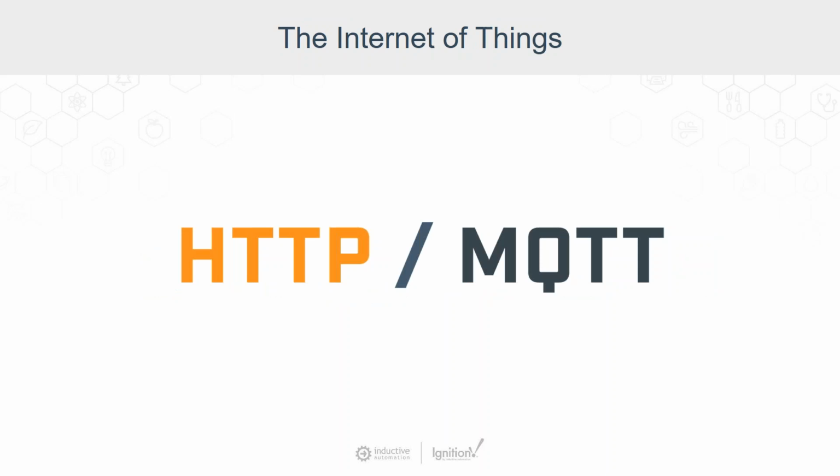And what I'm trying to do here is explain that for the industrial world, and getting these applications and the data that's there, we are equating the Internet of People to the Internet of Things. So for the Internet of People, it is HTTP and HTML. For the Internet of Things, it is MQTT and the Sparkplug specification, which is, again, that open payload specification for what is being transported. So MQTT is the transport mechanism, and Sparkplug is what is being transported.